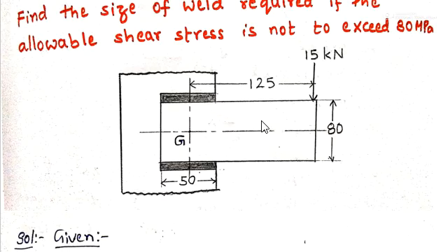So in that process, when it is rotating about the center of gravity, a shear stress is produced in the weld sections at so many points. So here the load is trying to produce primary and secondary shear stresses in the weld portions.